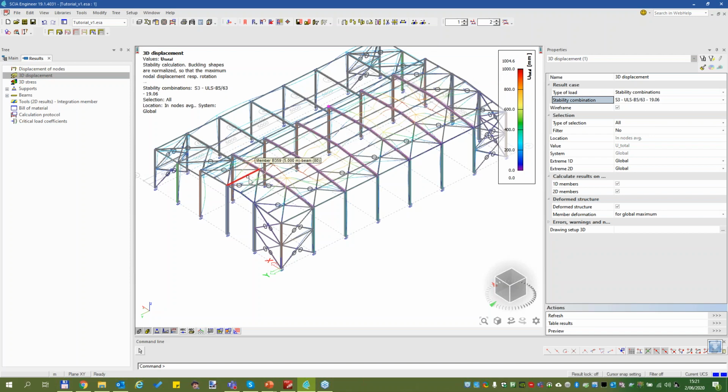And by doing that, the Eurocode also states that there's no need to consider flexural buckling. So once you do this, the flexural buckling check becomes obsolete, which means the whole KY, KZ buckling factors are no longer relevant. That's the reward you get when you do a real second order analysis. You can forget about the KY and the KZ factors. I will show that also in the next steps.